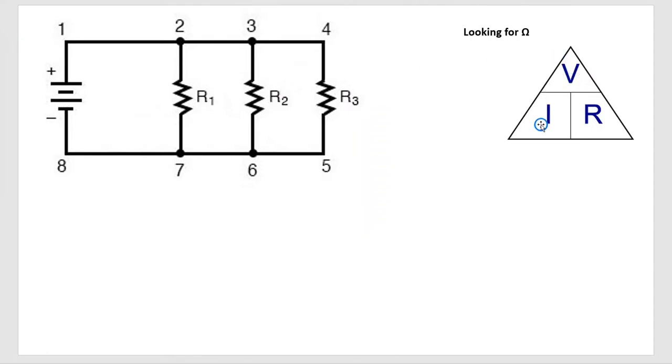using Ohm's law, which is right here, we know that to find anything, we need at least 2 other things. So right here we can see if we want to find voltage, we're going to need either amps or resistance. If we're going to find resistance, remember you put your finger over it, we're going to have to get volts and divide it by amps. And if we want to find amps, remember you put your finger over it and we're going to have volts and divide it by resistance.